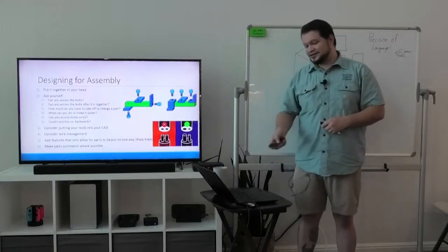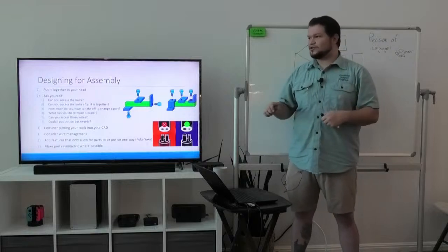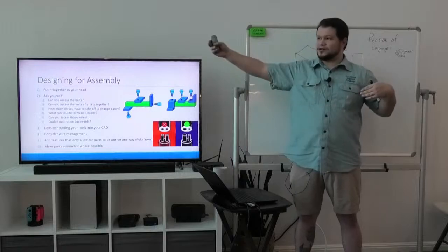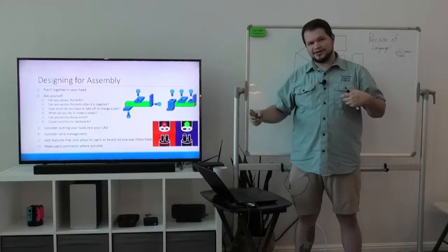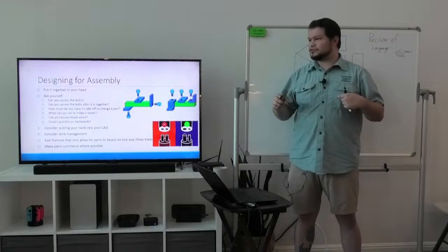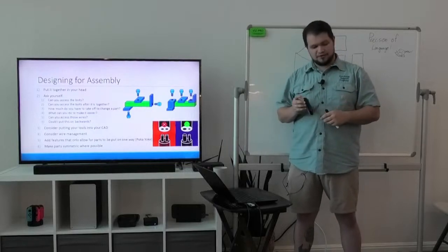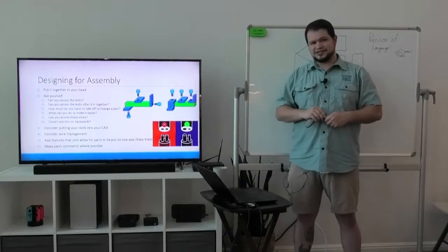When you consider your wire management, not only do you need to consider where the wires are running, but you need to consider motion as well. You have big, long linear slides, and you have something moving at the end, that thing needs wires to power it. And so throwing in cable tracks and ways of cable track being run will save you a lot of headache. If you leave that for, "I'll solve that problem when I get to it," it's a lot harder to find a place to fit it in.